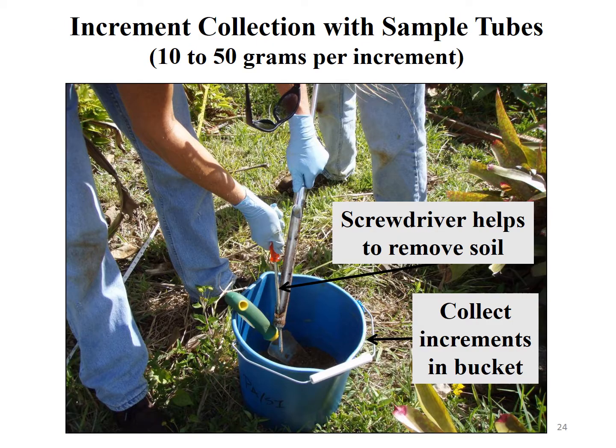For surface soil samples, each increment from a given DU MIS sample are placed together in the sample container, typically a bucket or heavy-duty plastic bag. The sample coring device does not need to be cleaned between each increment collected within a DU, but must be cleaned between use in separate DUs.